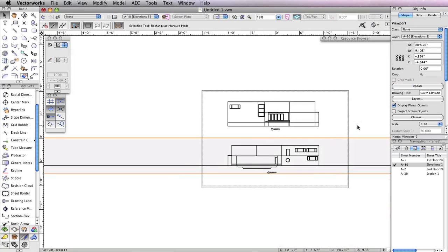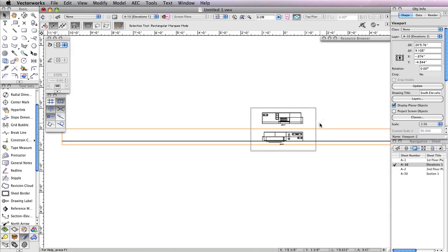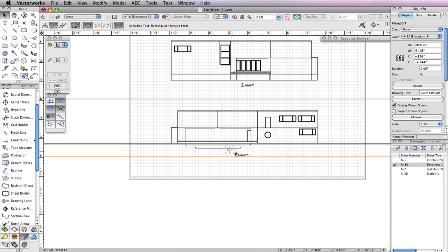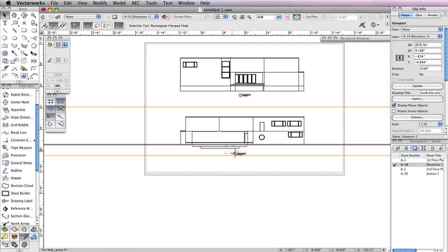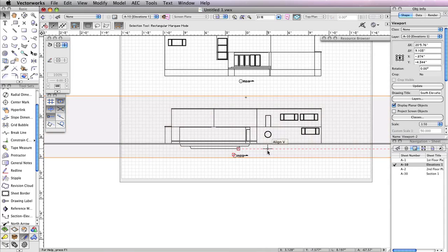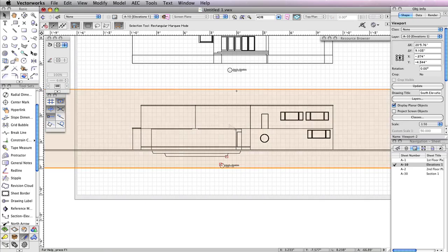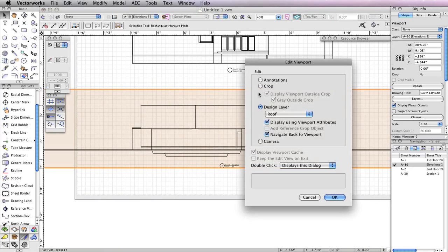You can see that the ground extrude currently extends much further than the page boundary, and that the circular floor from the auditorium is protruding through the bottom. The best way to fix this is to crop the viewport. To crop the viewport, right-click or double-click the viewport and choose Edit Viewport Crop.